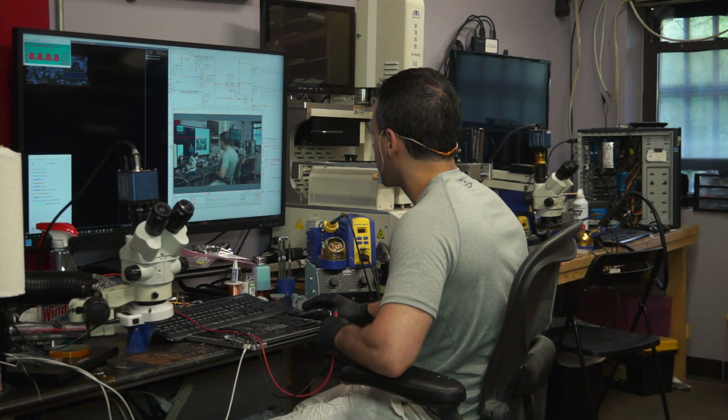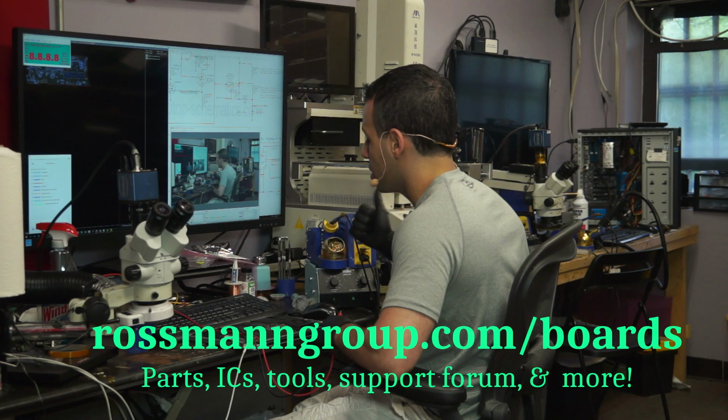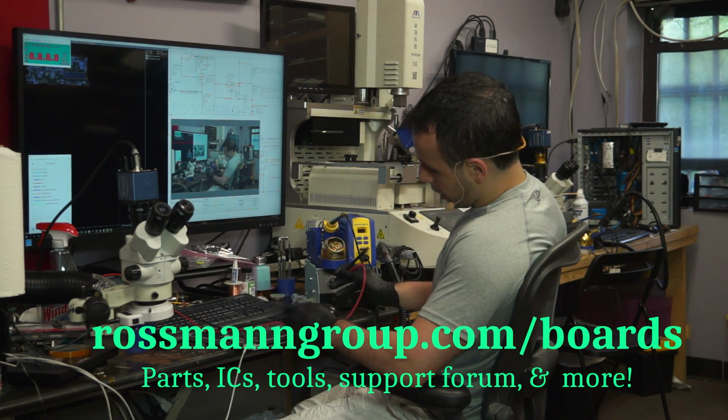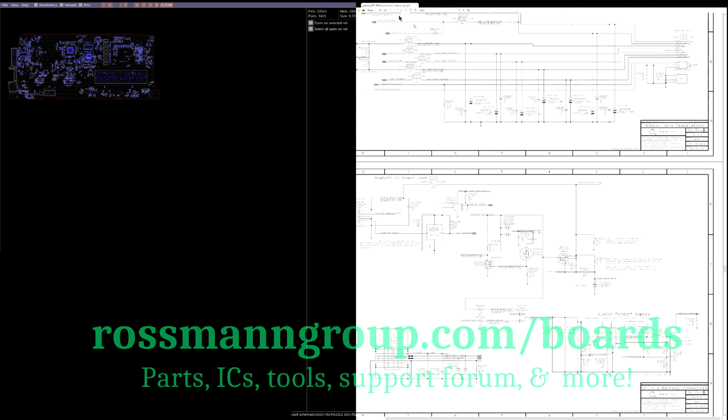So here we have, it says no image, and I want to see if it's actually no image, no backlight, or no CPU. So it turns on. I could feel that the CPU is getting a little warm. So the first thing I want to do is see if the CPU is getting power.